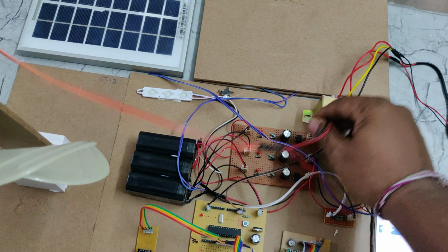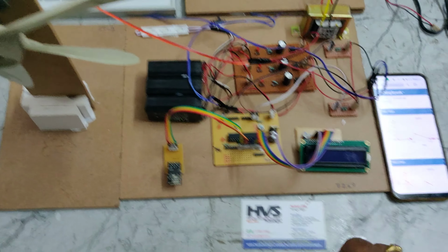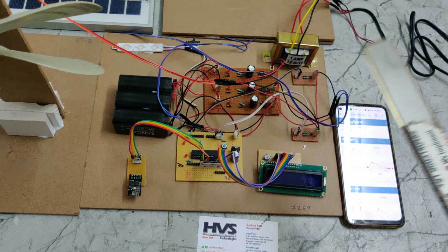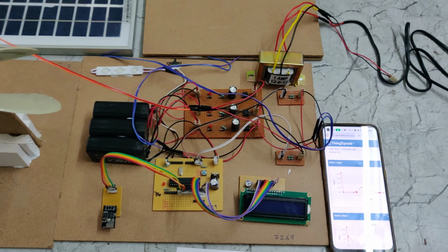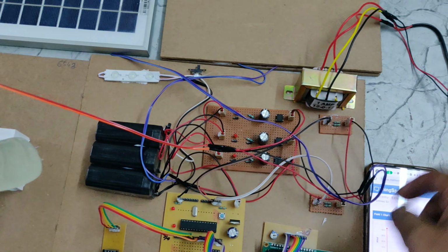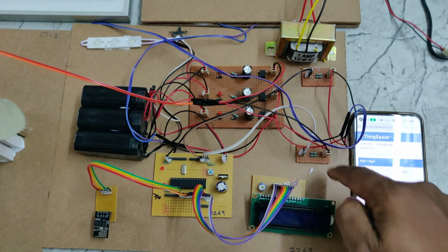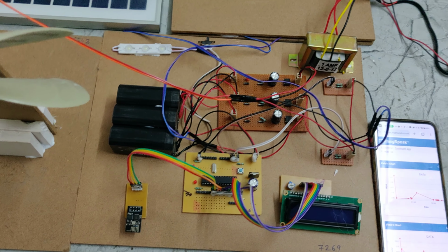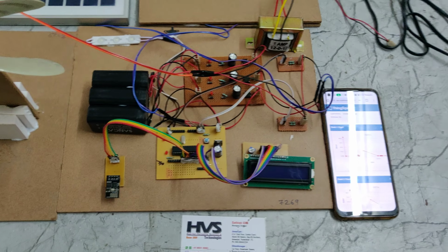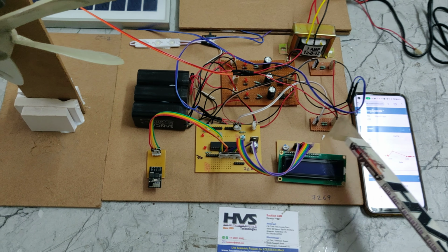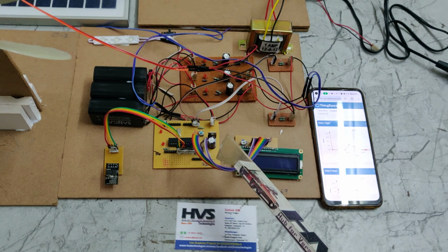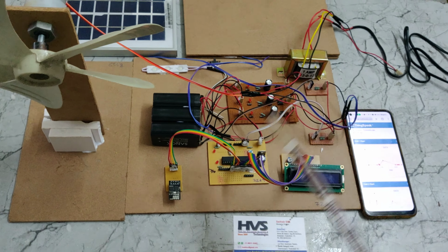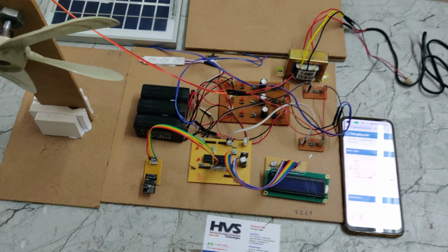Now connect the battery over here and the wind over here. We have connected these three sources to the microcontroller directly through these voltage sensors. Each voltage sensor consists of two resistors connected in series, as we are using a 10:1 voltage ratio. Whenever the input of this voltage sensor is 12 volts, the output from this voltage sensor is 1.2 volts. So in the microcontroller we write logic to multiply that by 10, as we are using the 10:1 voltage ratio.